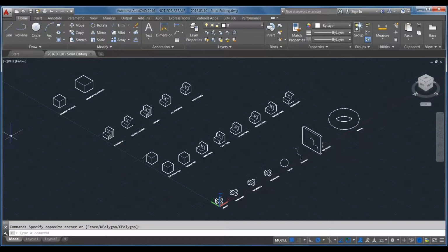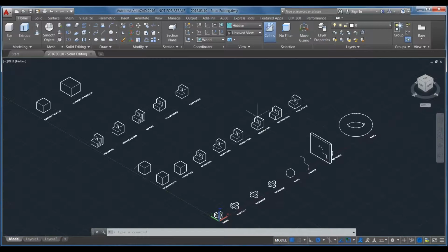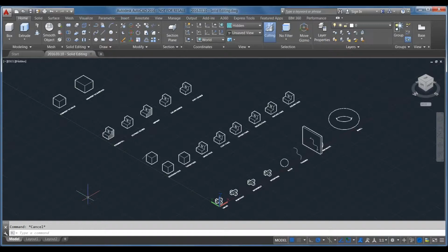So I'm here right now in AutoCAD. I just reset it to defaults this afternoon to show you how I would get to the 3D tools. So I'm going to go down here to my right-hand corner, click on the workspace gear, and switch to, now you have the 3D Basics workspace, which we worked in before. I'm actually going to switch to 3D modeling to get to that full functionality. This has all of the 3D tools you could ever want in AutoCAD. So again, that's the workspace gear down on the right-hand corner. If you're following along, click on 3D modeling and it'll bring you into that 3D modeling workspace. And I'm just going to dock my command line so that it's not distracting anybody.